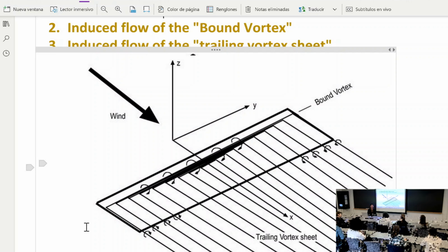But most of the time, as in this example, the lift vector seen by the individual airfoils tilts backward relative to the lift vector of the whole airplane. That backward component of the individual airfoil cross-sectional lift, added together, is the induced drag of the airplane. Okay, make sense?